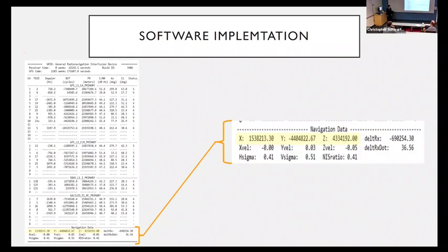Okay, so here we see the output of a real-time file that is generated by the GNSS receiver. This is a text file, and it reports the position of the antenna phase center in ECF coordinates, which you can see here. It updates this position at 1 Hertz. So what I did was I wrote some Python code which monitors the position reported here and then compares that